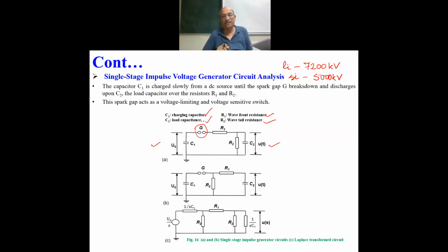So, for a specific gap distance between two spheres of a specific dimension, the breakdown in air would always take place by application of the same voltage, and that is what is required in this circuitry.